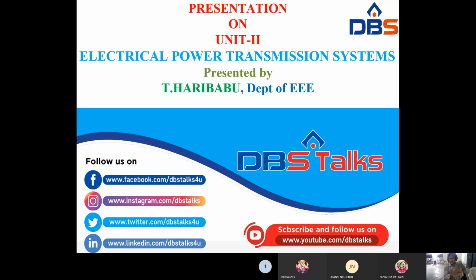In the regulation and efficiency concept also, I explained the phasor diagram. Let us take VR as the reference, because we know the VR value. That's why we take VR as reference. I know the IR value, that's why we take the IR R drop and IR XL drop.